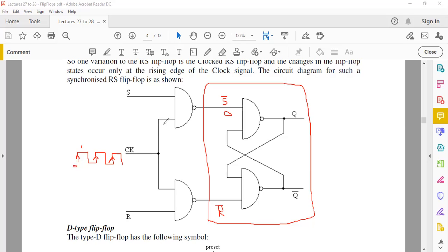So when this pin is 1, the question is, when do we get this 0 here? It is when this one is also 1, because it's a NAND gate. This is why S here is high. It's not complemented, because the desired change to get a 0 here is when S actually is high. Similarly, if you have your clock which has rising and falling edges, you want a circuit which does the desired change only when you have a rising edge.